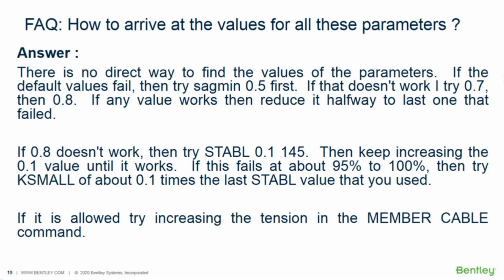Okay. And as much as possible, if it is possible to increase the initial tension in the member cable, you try to increase it so that the analysis will converge faster.